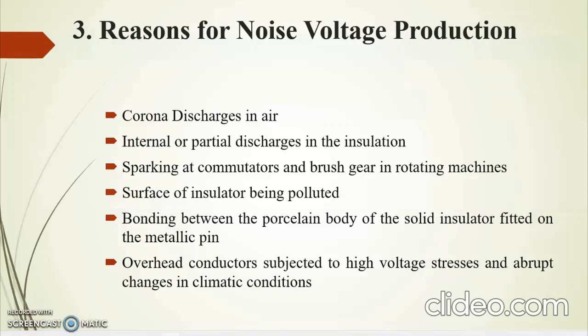The main reason responsible for production of noise voltage may be the overhead conductors, which are subjected to very high voltage stresses in case of abnormal or faulty conditions such as lightning or short circuit conditions. We can hear noise voltage. Also, the noise voltage can occur due to abrupt changes in the climate conditions. So that's all. We are going to the next slide.